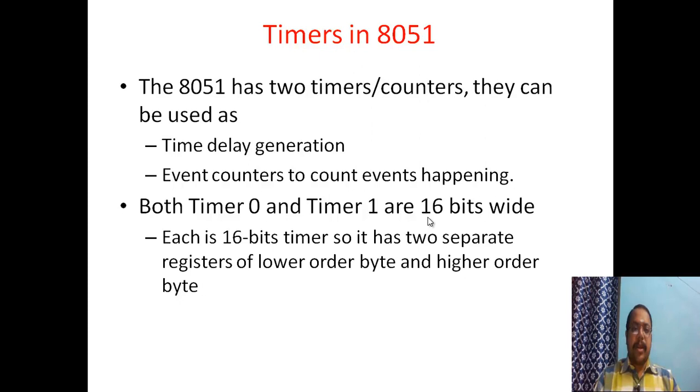When it is being operated with the internal clock, we call it a timer. When it is operated by an external source, it is called a counter. For example, from any sensor you will get an input. When you go for car parking, when a car arrives, the count will be incremented. Timers are incremented at a regular interval, whereas counters are not incremented at regular intervals.